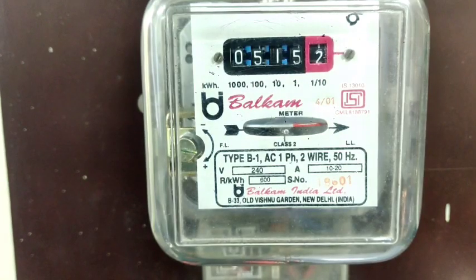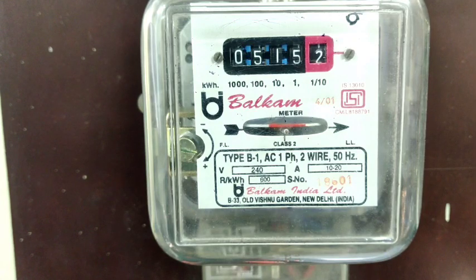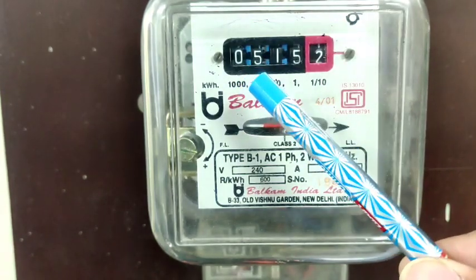So by initial reading, I mean the reading of the energy meter before turning on our load, meaning we have not turned on our light bulbs yet and we need to find out what the initial reading of this energy meter is. Only then will we be able to evaluate the energy consumed by these bulbs. And how will we do that? We'll do that by subtracting both the readings, meaning we'll subtract the final reading and the initial reading, kWh2 minus kWh1. So now let us see how to take the initial reading.